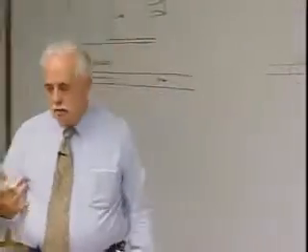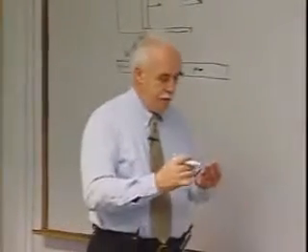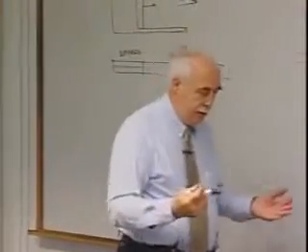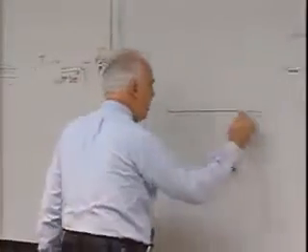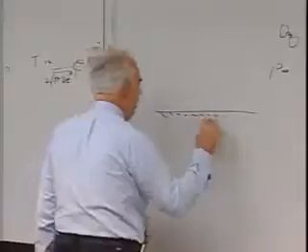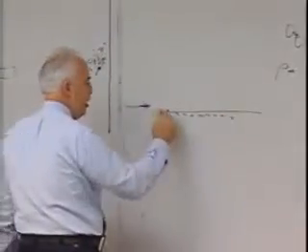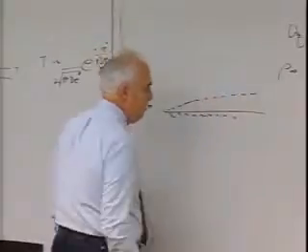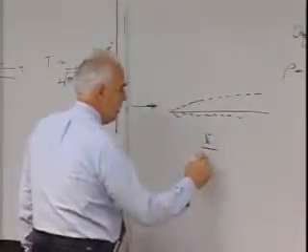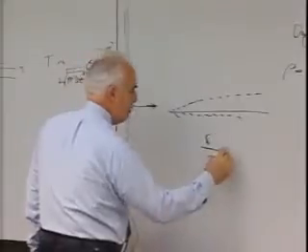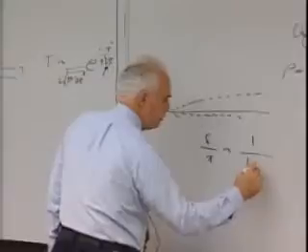It is also not thermal diffusivity, but if you now consider simplest fluid mechanics, flat plate, first thing you learn about in terms of viscous flow. You've got some velocity coming along here, you've got a boundary layer that builds up. The boundary layer compared to x varies as 1 over square root of Reynolds number.